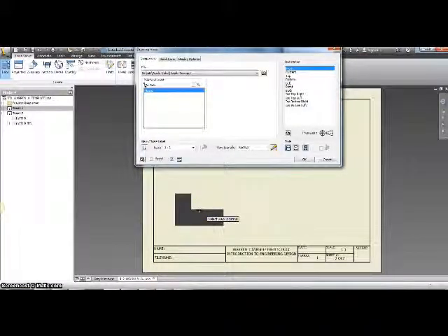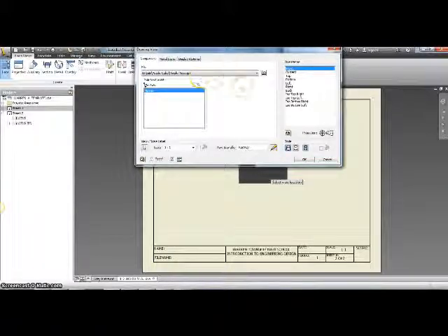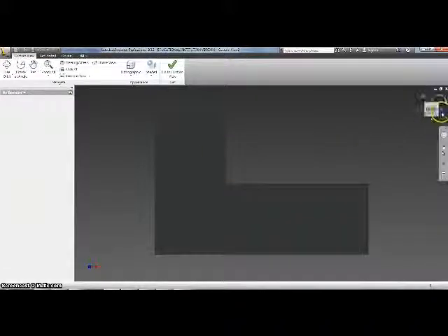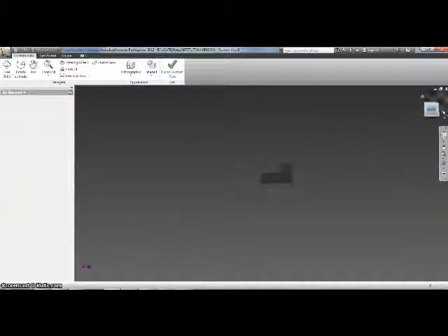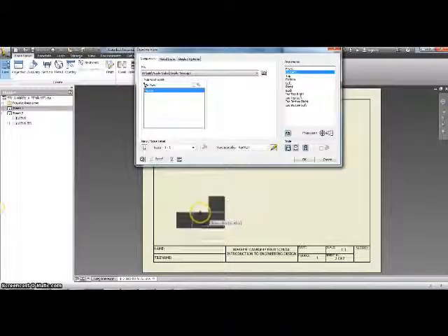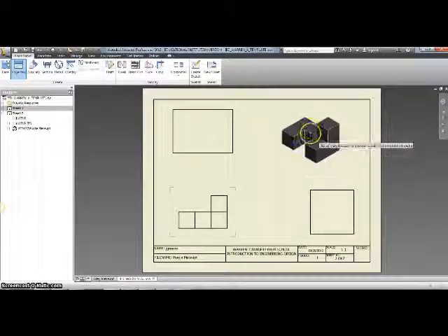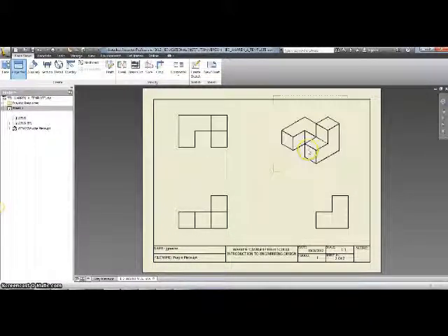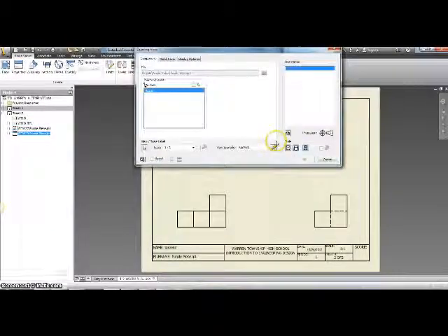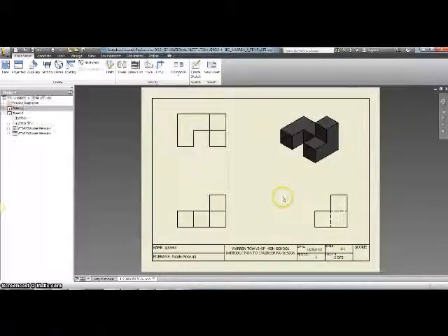and you can see now we want to flip that piece. So in our drawing view dialog box, we will go to change view orientation. Now we'll change the view orientation so our front view is now our back view. We will select Finish Custom View, and you can see now that those hidden lines are now object lines. Our scale is 1:1, so we may place our front view, our top view, our right side view, and our isometric. Right-click, Create. Once again, we can double-click our isometric, select Shaded, and we now have an isometric shaded view.